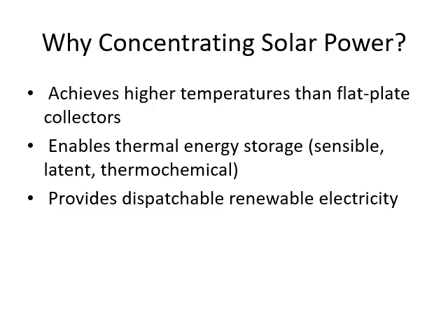So why do we need concentrating solar power? It is because the higher the temperature is, right? If you have gone through the Carnot power cycle, you should remember that a higher temperature will always increase the cycle's efficiency. As I have mentioned, the temperature can be up to 2000 degrees Celsius, which is quite high for generating power or any other application.